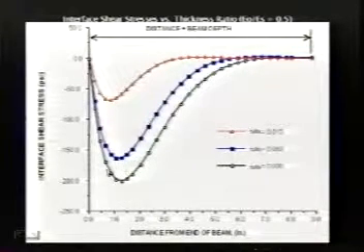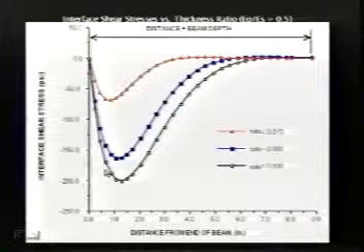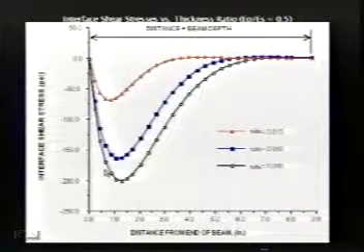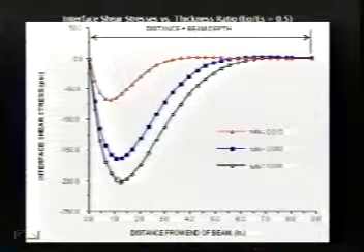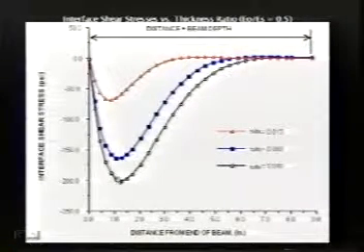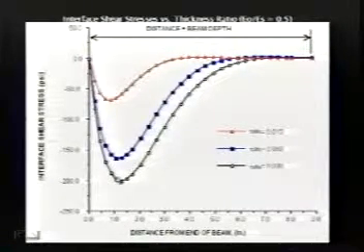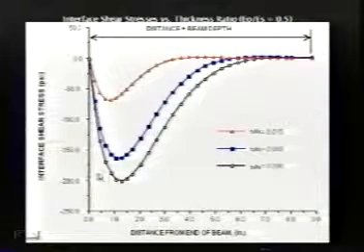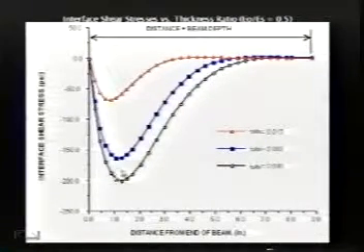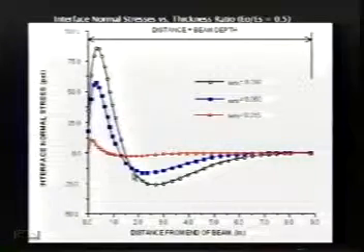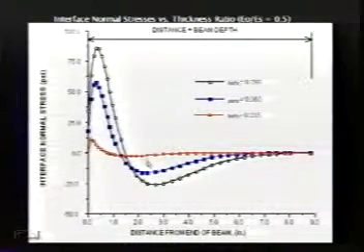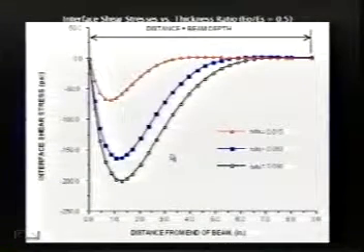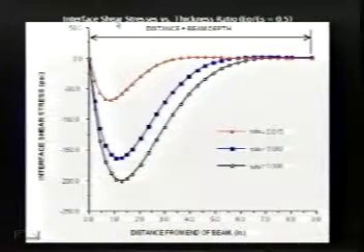And that's something I think we intuitively knew, but it certainly helped to see that mathematically. So that tells you that going to a really thick overlay probably isn't the way to go. Use the minimum thickness overlay that you can get by with, and you'll end up with less stress in the system. And by the way, that previous one was for interface shear stresses.